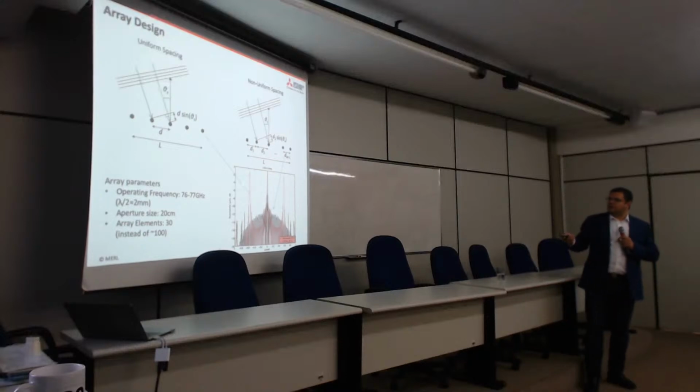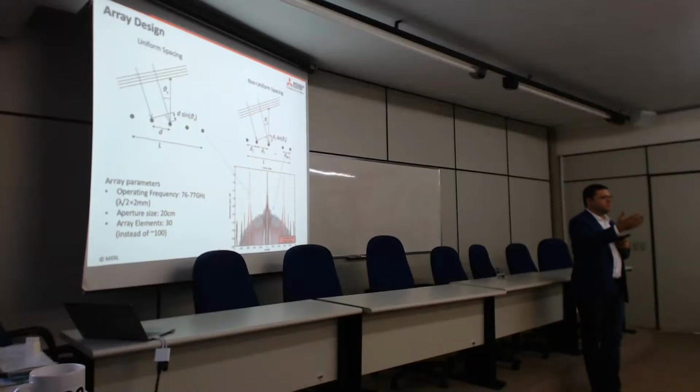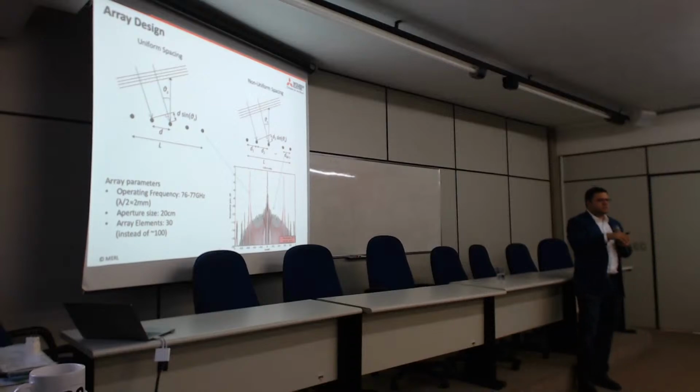Okay, so the bottom line here is that you have higher side lobes. If you were to do some conventional processing, what that would mean is that your signal would be a bit more blurred, and if you had a reflector, you'd have a bit more interference on the sides of it, but you wouldn't have fundamental ambiguities.